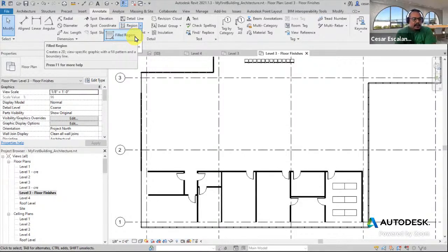It can be connected with some Revit elements, like I can lock and create alignments with the elements underneath. Well, they are view specific. And what that means is that they are not part of the 3D model. They're just representational in nature. They don't modify the model. But they will only display in this active view.